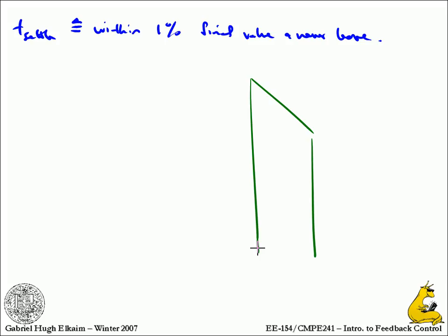Yes. So what they're doing is they're trying to keep the building vertical at all costs. The top 3 floors of the building are a big giant cast concrete weight that's supported on air bearings. They've got a pump that blows air underneath and floats this huge weight, and they've got huge actuators on all sides of the building that push against this weight to move the top of the building.